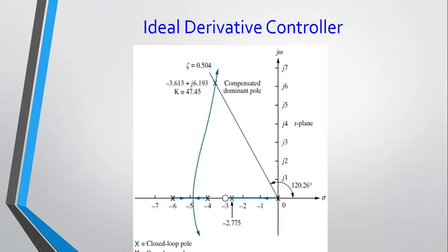So this is your new root locus now. The shape has changed considerably, but importantly here, your root locus is now going through the point you want to be situated at, and from there, of course, you can work out the gain that you need to set on the system. It won't be the same gain as before. So you need to find out the gain at which this point is obtained, and this is what you're going to tune your compensator to, and you expect to get the transient point.